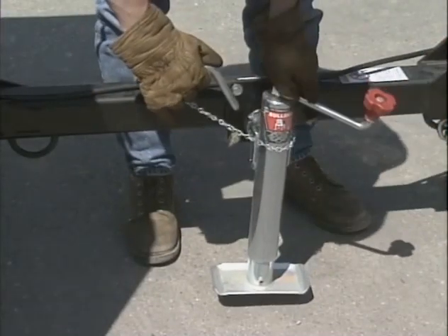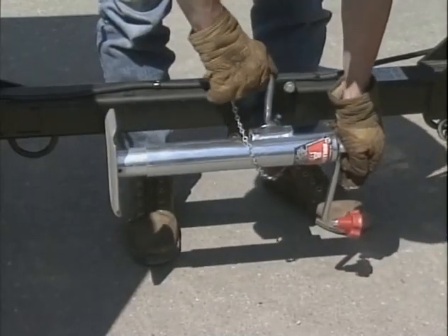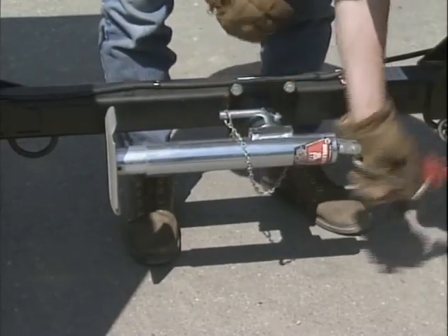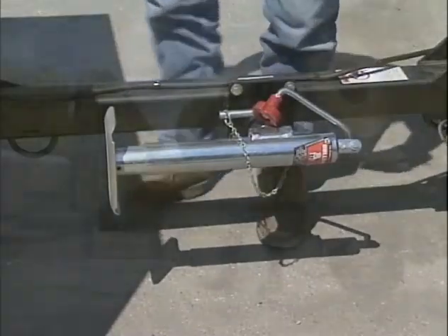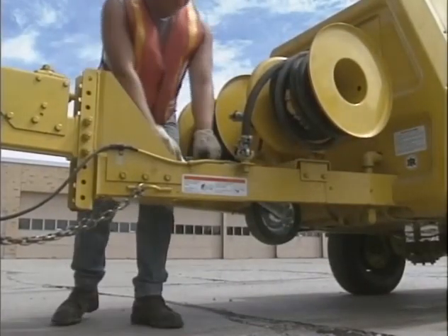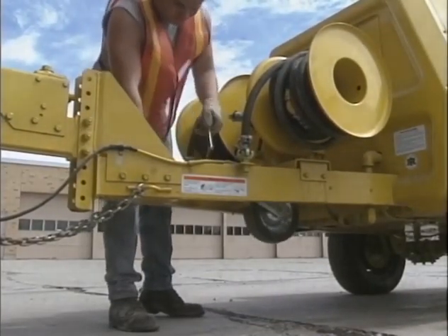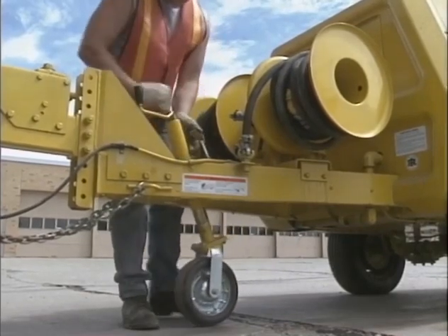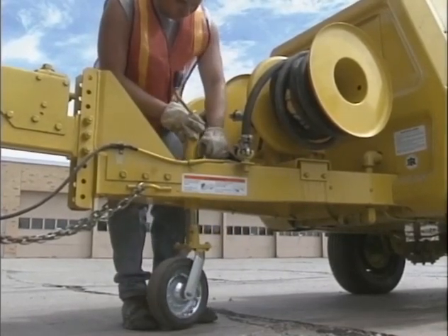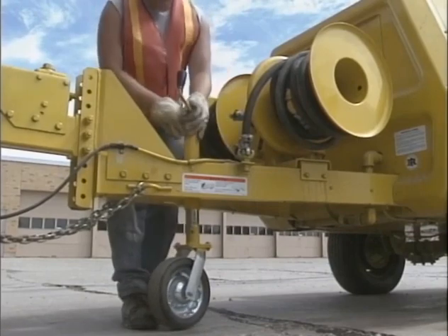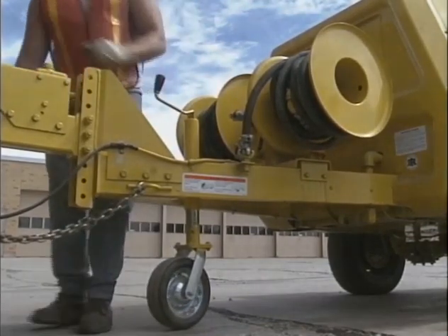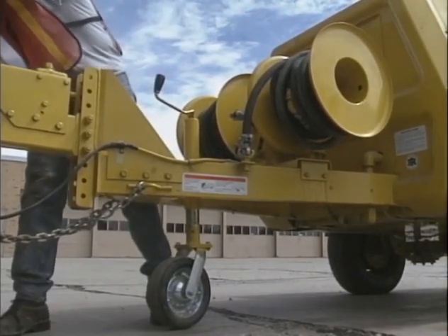On two-wheeled machines, fully retract the front screw jack if provided and any rear stabilizer legs. If a retractable caster wheel is provided, pull the lock pin and fold and raise the caster wheel, then make sure the pin is re-engaged to secure the caster wheel in full up and locked position. Keep hands and fingers clear of pinch points.